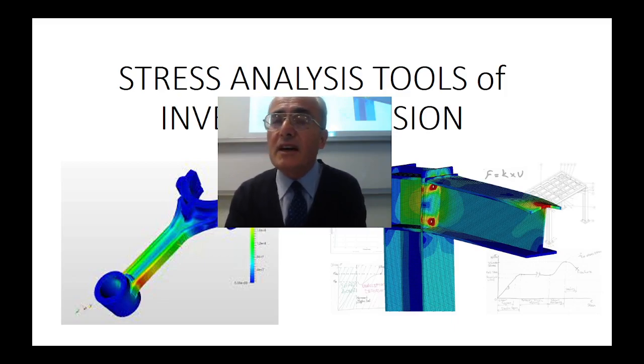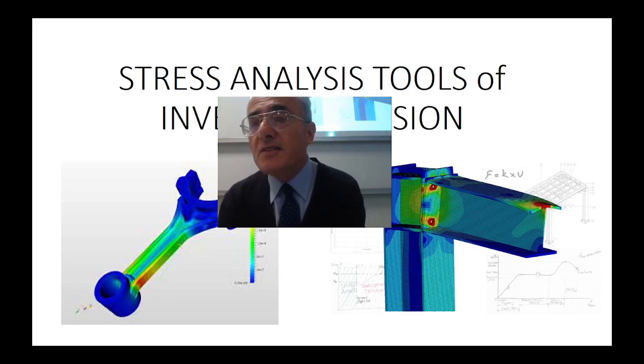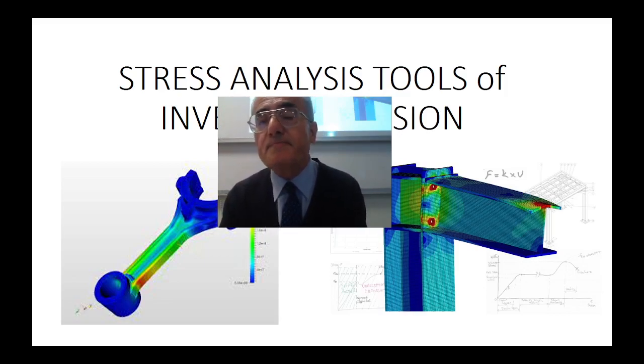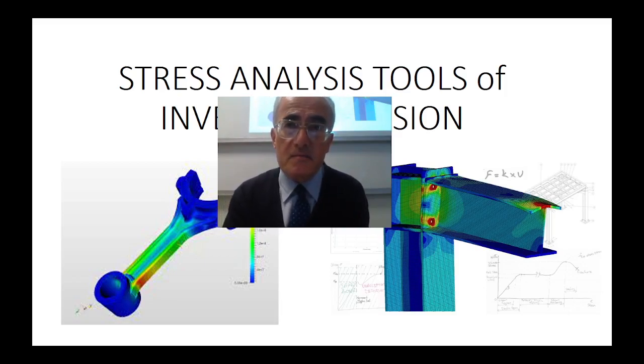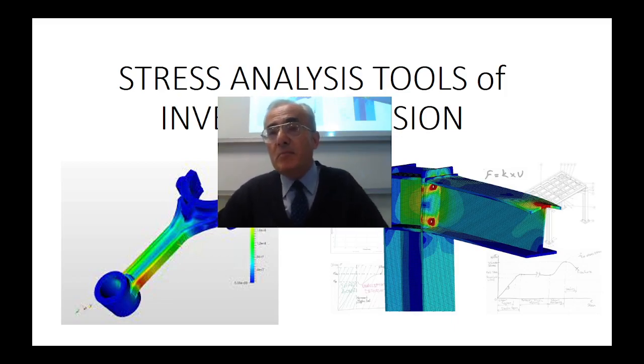I think from the outcome of the mechanics of materials course, if there is a sharp, abrupt geometrical change, so over there you have a sharp edge, a sharp corner. Yes, over there will be stress concentration. The maximum stress is expected in the vicinity of such a part. So, be able to find the stress value more accurately, because that part is critical.